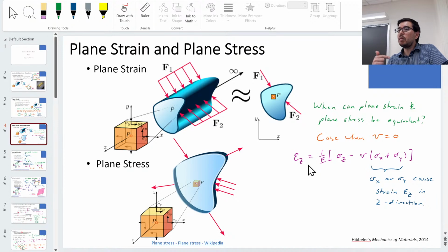And when we were doing it with the stresses by themselves, we don't think too much about the Poisson ratio. That's not completely true, because we have tau equal to G gamma, okay? And G, the shear modulus, has dependence on the Poisson ratio.